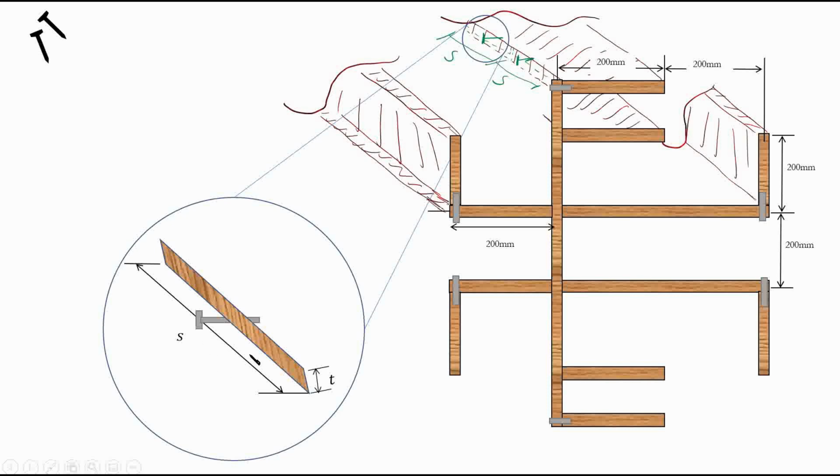And we can find it. So basically, this is the tributary area for this nail. This nail is transferring the shear stress from this segment to this segment, right? And what is that portion? It's the spacing multiplied by the thickness. That's the area that this nail is covering. Again, we can visualize what the tributary area for each nail is.